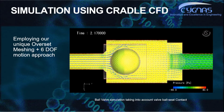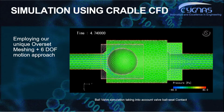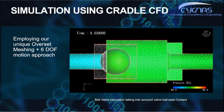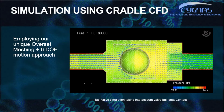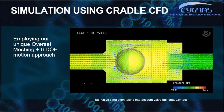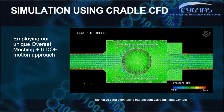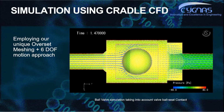In this video, the ball in the ball check valve is represented with an overset mesh and with 6 degrees of freedom motion. This means that the movement of the ball in the valve here is given by the force and moment balance acting on it. In case of rigid motion, Cradle is able to handle this alone without any co-simulation, and it can take into account a spring force, a resistive torque and so on.